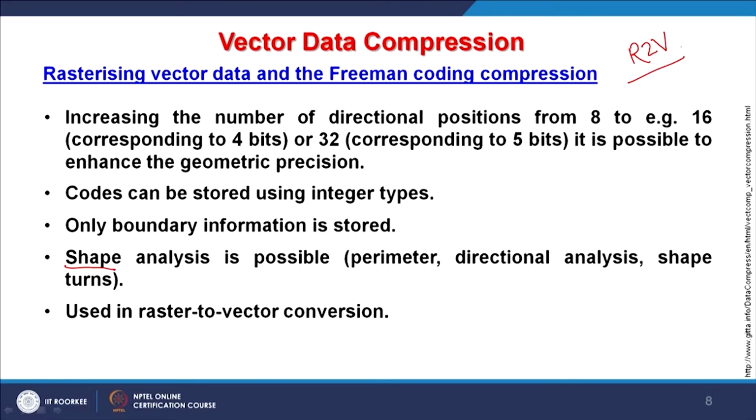We give a start to the software, saying this is the start of a contour line having value 100. Then the software itself, by identifying pixels having the same color characteristics, will follow and digitize or vectorize. And wherever there is a confusion, it will stop. Now, when human intervention is required to proceed further, you have to connect by yourself.